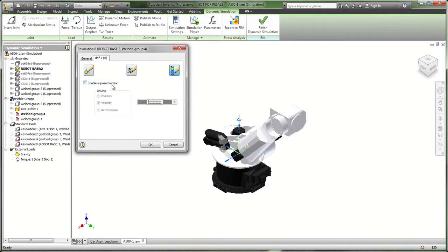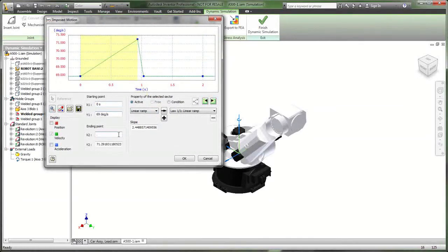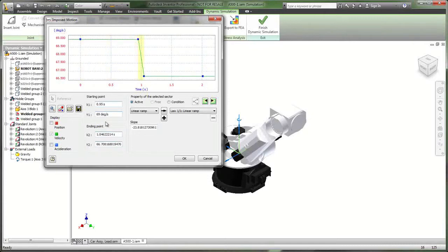Next, we will look at the 2 most significant seconds of motion taken from the movement profile for the manipulator arm during the course of the ride. We are basically breaking up the 2 seconds into segments of motion. We are moving about 69 degrees per second, which is the maximum rate of rotation for this manipulator. There is a 180-degree change of direction, essentially going from positive 69 degrees per second to negative 69 degrees per second in the opposite direction.